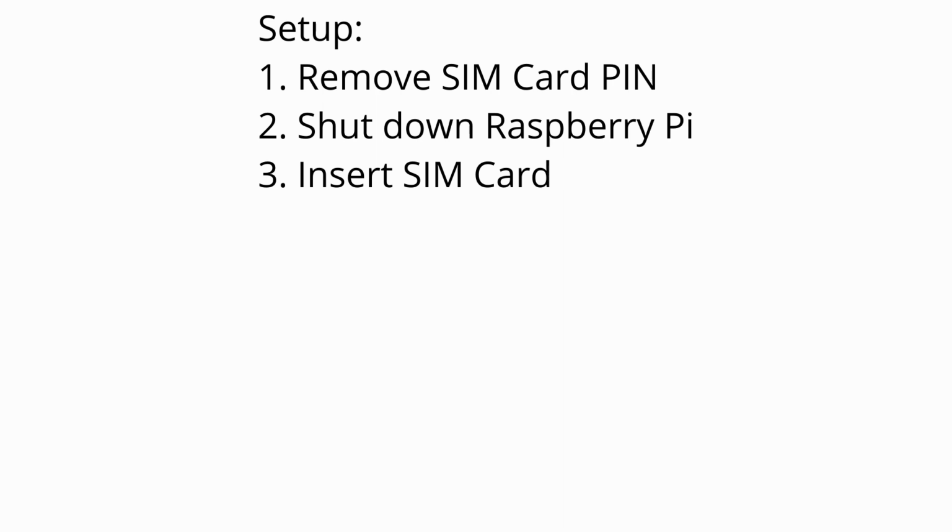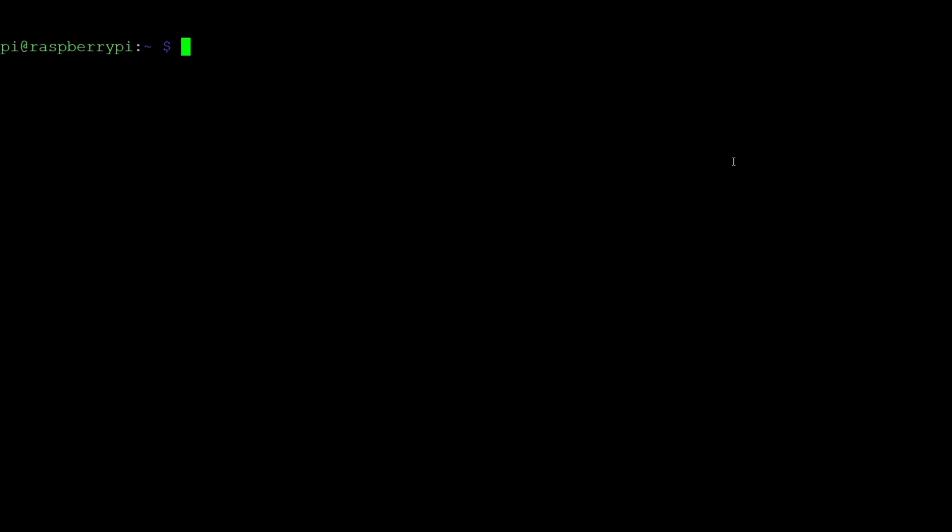For a tutorial on how to do this and how to open the housing, please visit the video that is linked here. Afterwards, we can proceed to install all necessary software. First, log into your Pi using SSH, I did this via PuTTY on Windows, and then run sudo -i, since all of the commands that we need to run actually require root privileges.